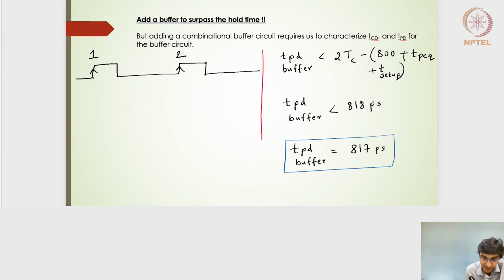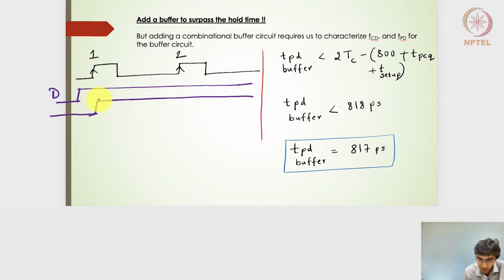So let's say that the D signal has arrived much earlier. So this is the first input to the flop number 1, or the flop input. And then the output is getting captured. Let's say that the output is getting captured here just soon after the first clock edge. So this will be my contaminated CCQ, contaminated clock to Q.